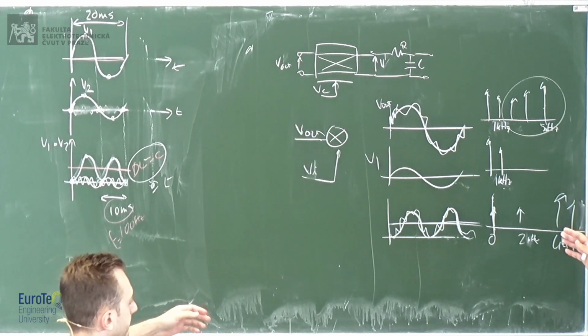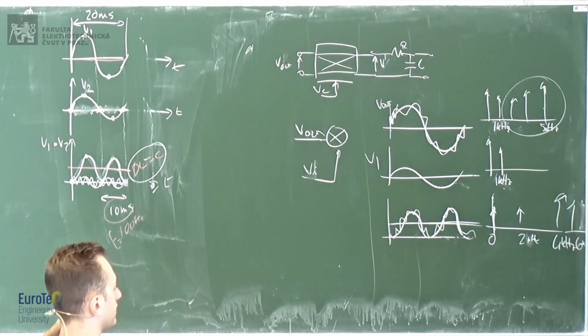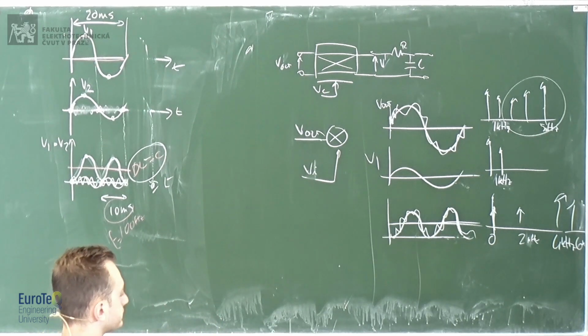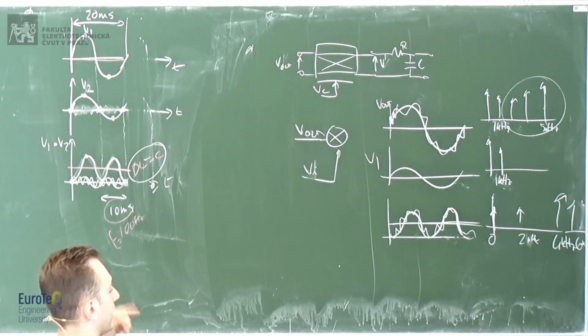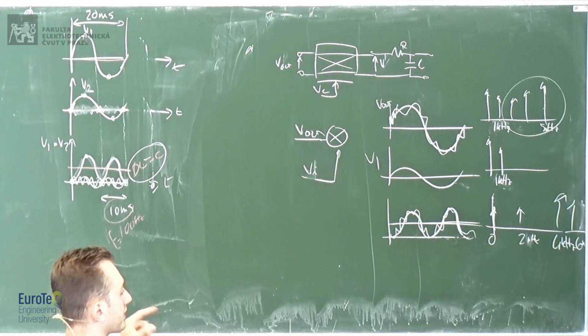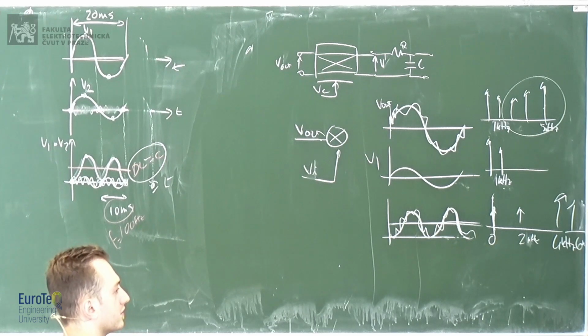If you want to measure the imaginary part, you simply have a phase shift. If your real part is V out, that means cosine phi is 1, which means it's not imaginary at all. But if cosine changes a bit, you know there's an imaginary component. How do you know that? Because the average value is not equal to the magnitude of V out. So that means the cosine has a component. But you don't know the amplitude of V out. That's the point.